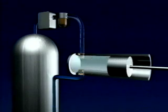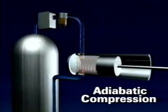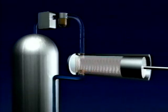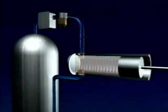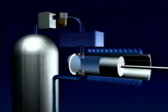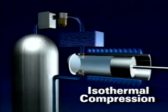Compressing air generates heat. If the cylinder retains all of this heat, there will be a condition called adiabatic compression. Theoretically, 36% more power is needed to compress air when the heat is not dissipated. An intercooler and water jackets or oil jackets are used to remove some of this heat. If all of the heat is dissipated, this is called isothermal compression.